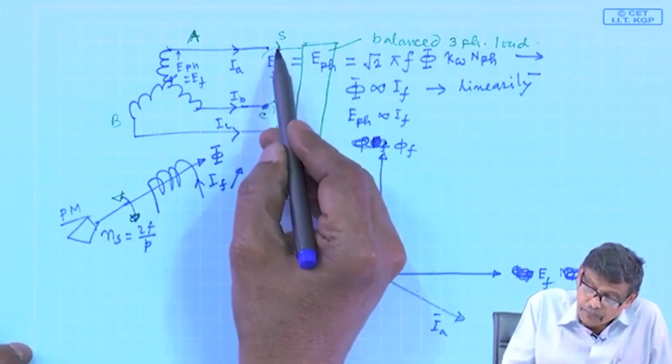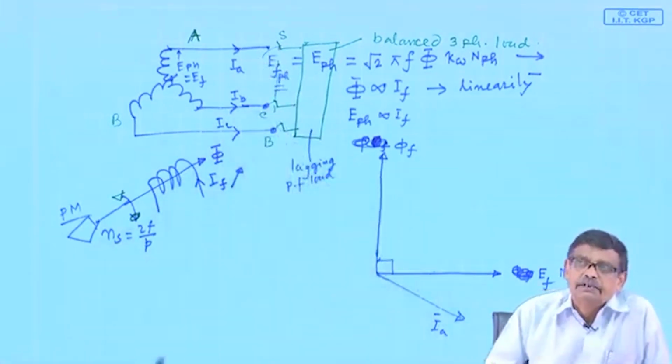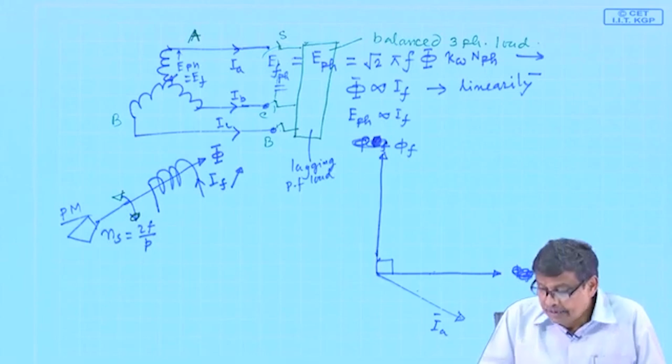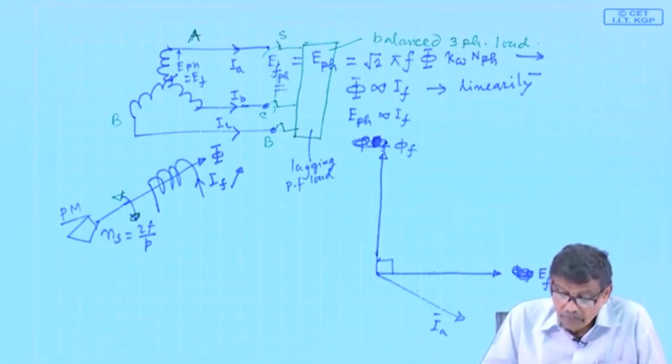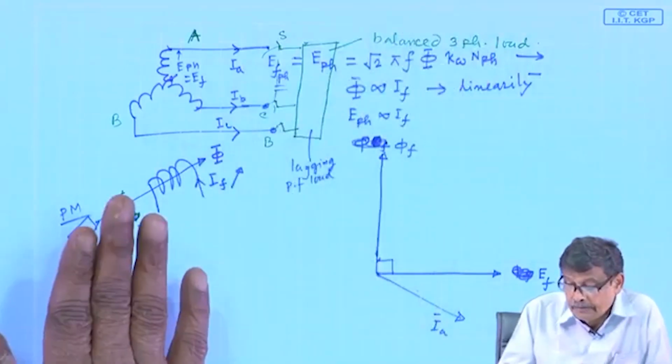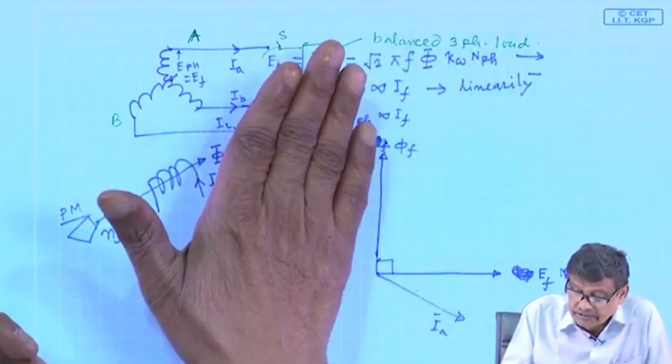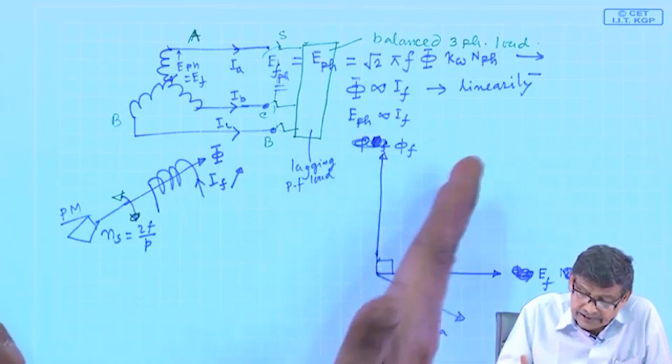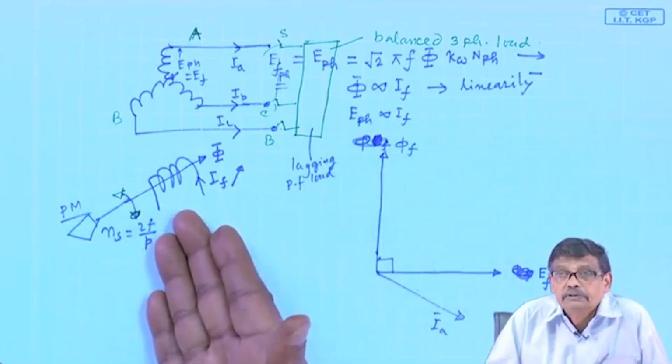Now, the moment you close this switch, drama starts, in the sense that so long as the switch was open, the air gap flux was decided by IF alone.